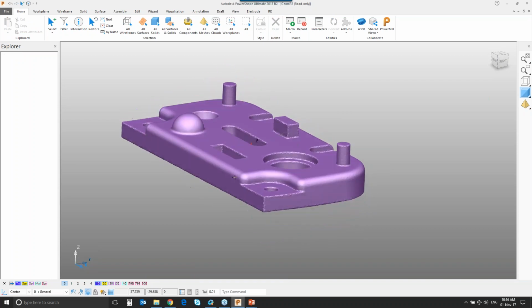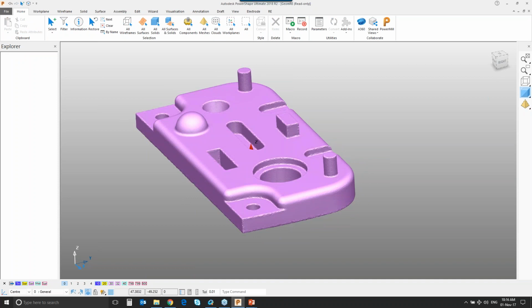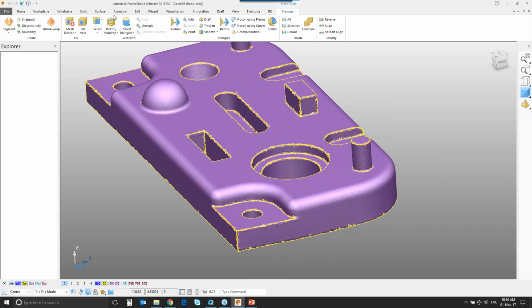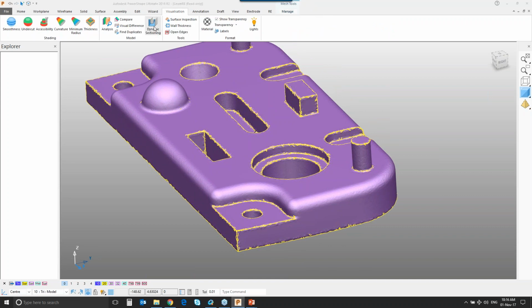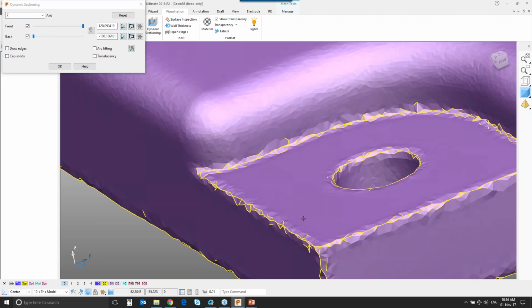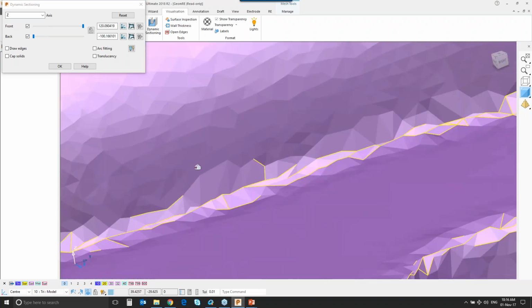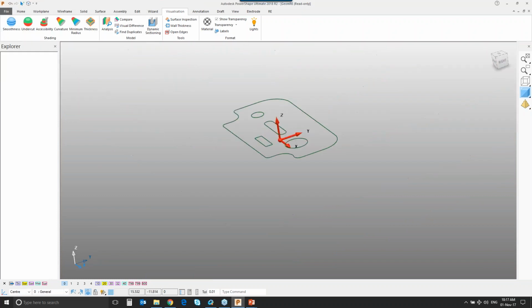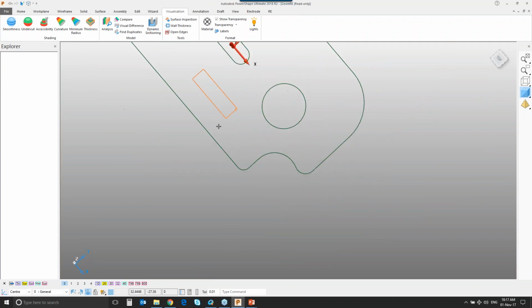And this is where you can really combine different techniques. Up until now, I've used pretty much exclusively the segmenter, both manual and interactive, to get to the stage I'm at. But here I'd like to use maybe some sectioning. Very straightforward to do. Let's select the triangle set, go to the visualization page and go for some dynamic sectioning. And on this page, I'm going to switch off and just use the front region for the slicing. Switch on that I'm working along the Z-axis, and then go and choose somewhere that I'd like to slice. So let's say somewhere around, click the button here to say I'd like to slice somewhere around this point here. I'd like arcs, so let's switch that on, and let's create our section. Now when I switch off the triangle set, you can see that I have information regarding that region.